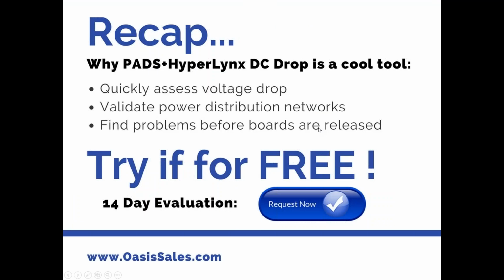Okay, so just a quick recap on why HyperLynx DC Drop can provide a lot of benefit to you and your organization. Quickly assesses voltage drop, validates the PDN or power distribution network, and find problems before boards are released. I think this is probably the most important aspect to HyperLynx DC Drop. Power integrity issues, a lot of people don't think about them until they've actually happened to their particular company. It can be very difficult to ascertain why it's happening, but it can just cause boards to fail. So if you don't understand your power distribution network, it can really come back to bite you.